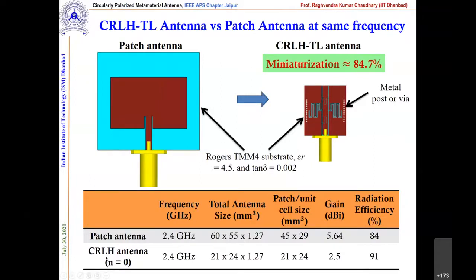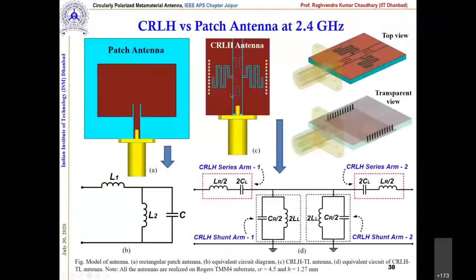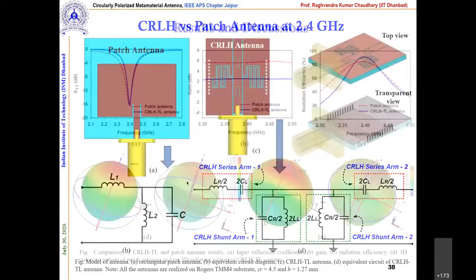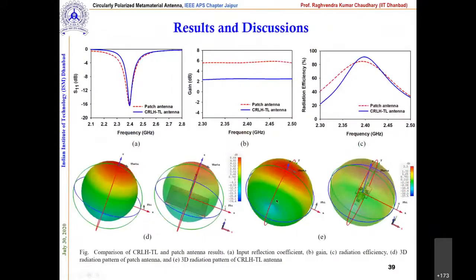So it is going to radiate in a particular direction. It is actually a directional antenna, like a patch antenna. In a particular broadside direction, it is radiating. Correct. So we are converting its omnidirectional pattern to this by adding the post. Correct. In this way, the gain is improved, and now we can say this is comparable to the patch antenna.